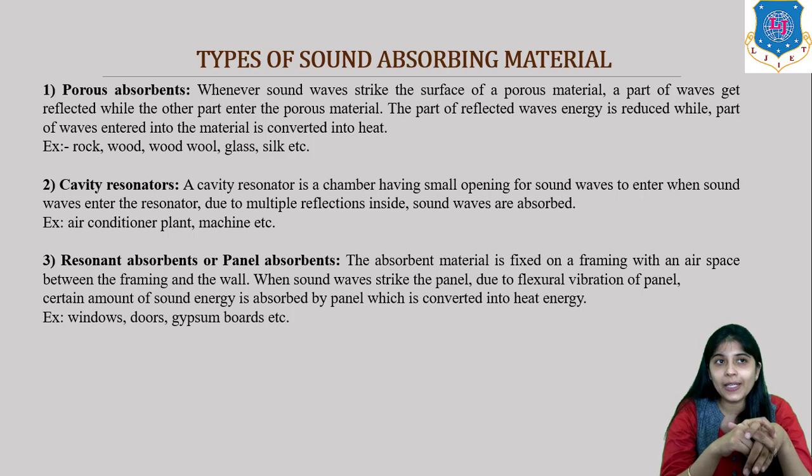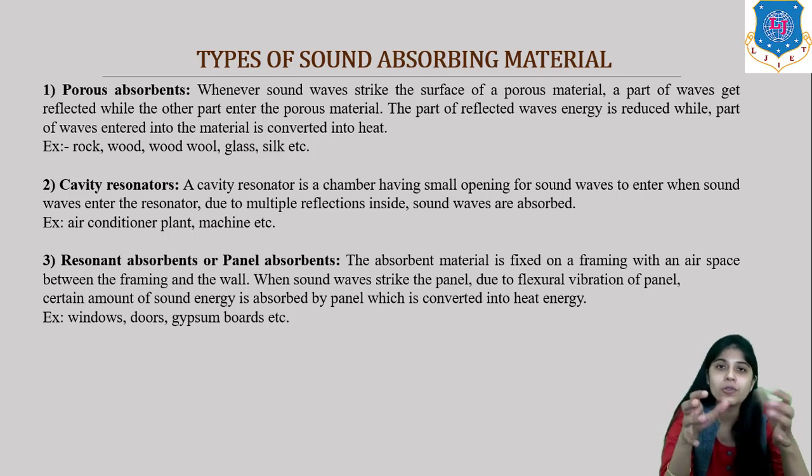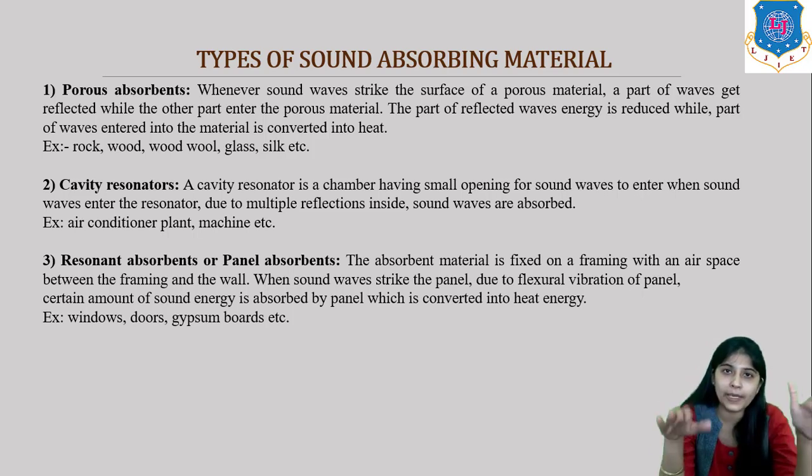So whenever the absorbent material is fixed on a framing with an air space between the framing and the wall, the sound waves strike the panel, and due to the flexural vibration of the panel, a certain amount of sound energy is absorbed by the panel, which is converted into heat energy. So you must have seen the window panel, right?